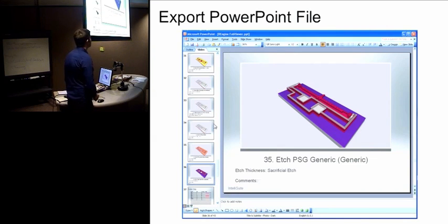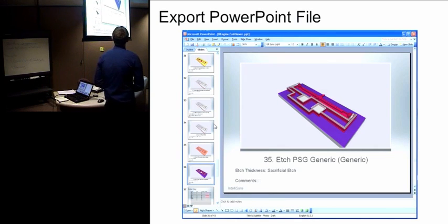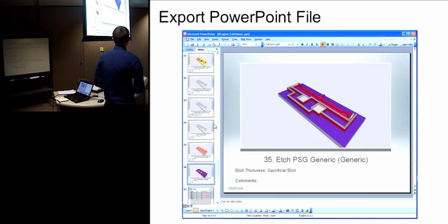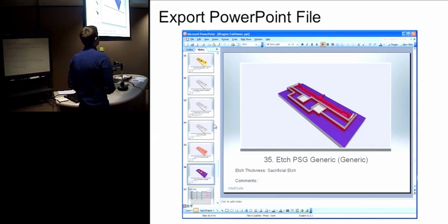This tool, FabViewer, FabSim, and the Blueprint cross-section viewer all can create these PowerPoint files where if you're looking at any particular cross-section or anything, it will just show you your current view, but for each process step. And then at the end, it will give you a summary of the processes used, the materials used, what all of the colors represent, and everything. And then from here, you can definitely edit these if you want to put them in some sort of different presentation. You can take the images out of it.